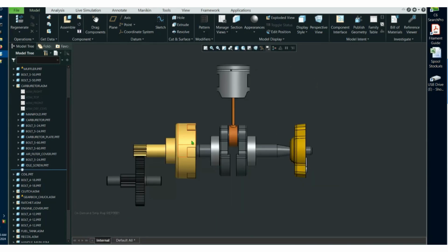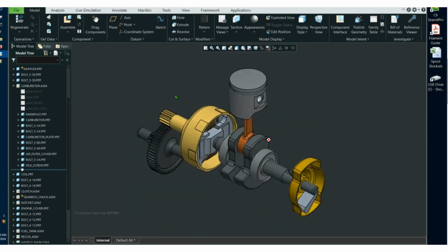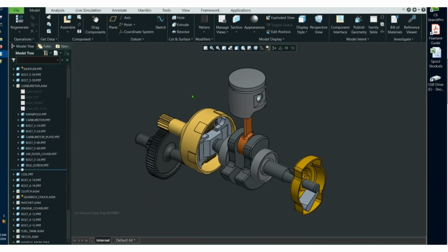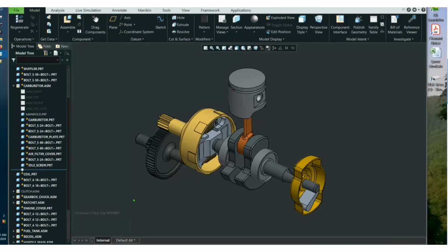The cool part about this, most significantly for those doing very large assemblies or assemblies that rise to the level of actually pressuring your computer in some way, is once I've done this, because I used a simp rep, I can come up here and I can do an erase not display, and I can blow all that stuff I've taken away visually out of memory. And that's why we advise nowadays to be using simple reps for the display of components and things like that, as opposed to using hide show, because hide show doesn't really bring it to a level where you can subsequently take away the math, if you will.